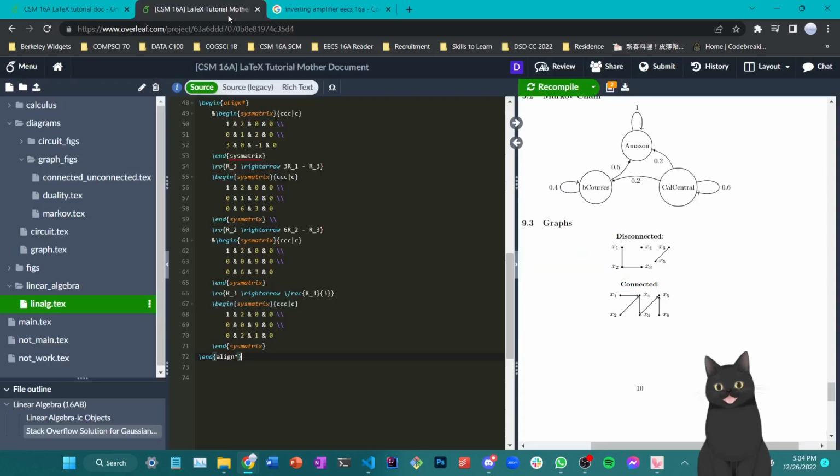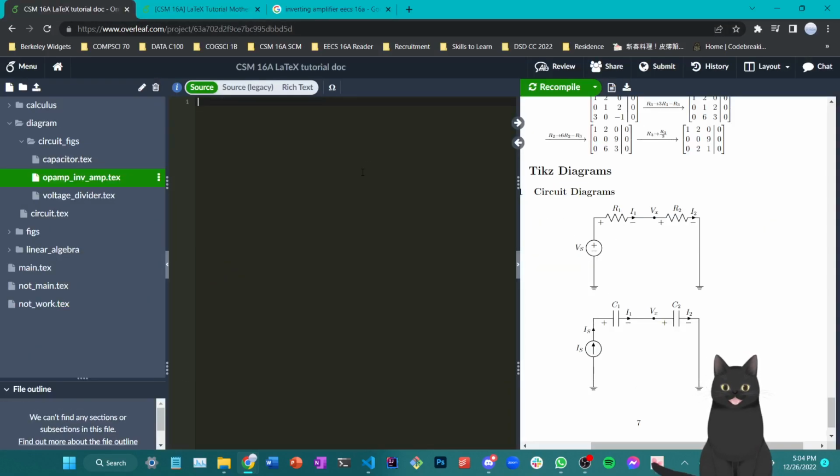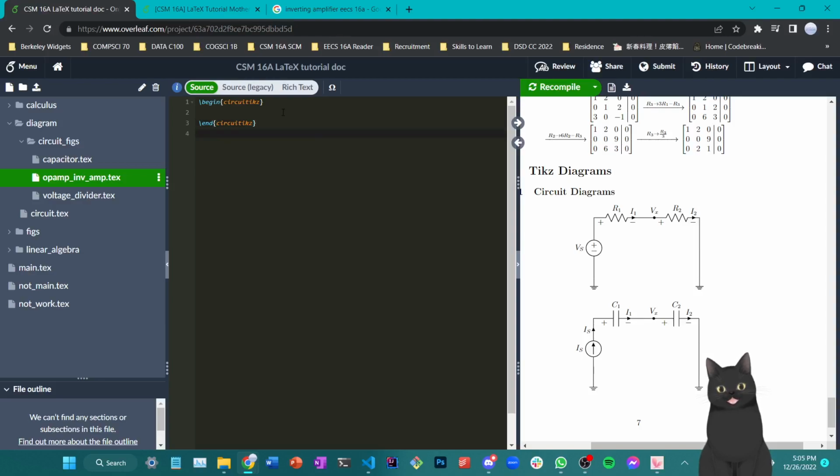in LaTeX. So first of all, I still need to start my circuit diagram with begin circuitikz, because this is just how we draw circuits. Let's also add an extra line at the end of the document, because I got roasted about it. Once again, you can scale your op-amp. This time I will not scale, and I'll only use the American option. And we do have to draw. 0, 0 is our starting point.